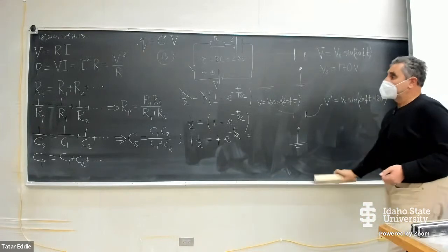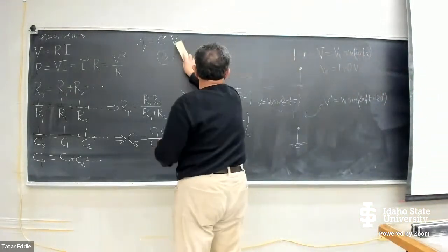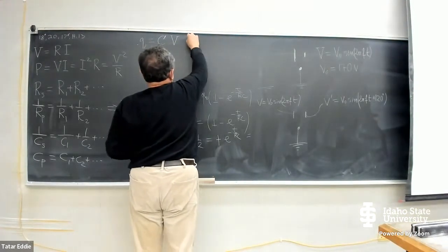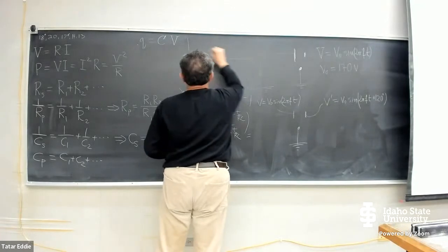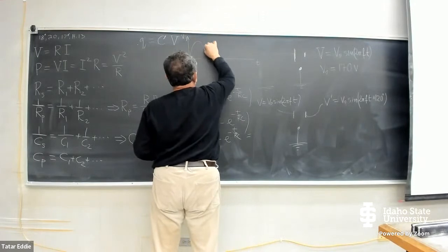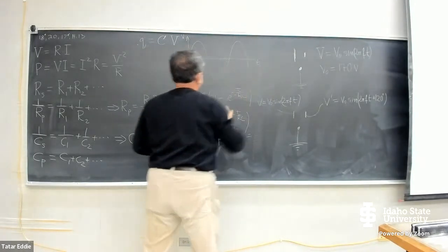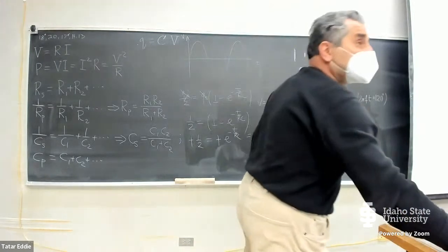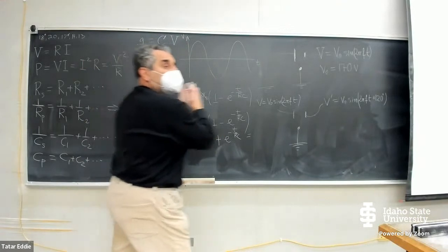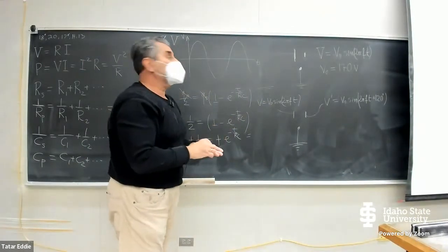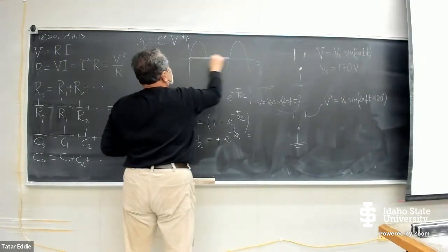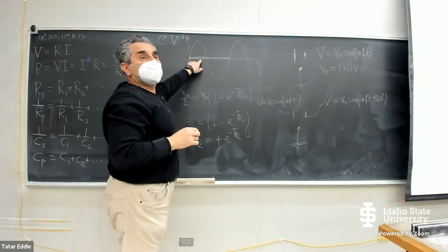So what does this mean? This means that if one of the terminals, the voltage changes like this, V as a function of time looks like a standard sine function like this. The other terminal provides exactly the same sine function, but shifted by 120 degrees. So this is one cycle. 1/3 of this cycle is 120 degrees.